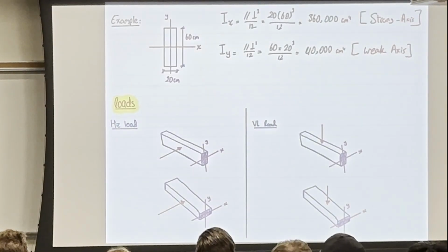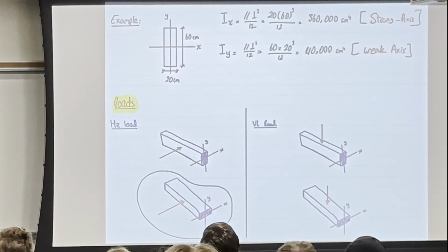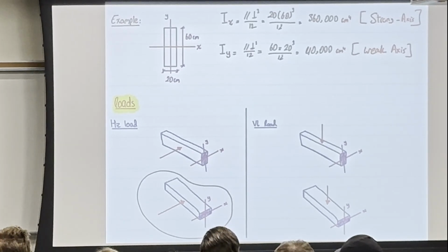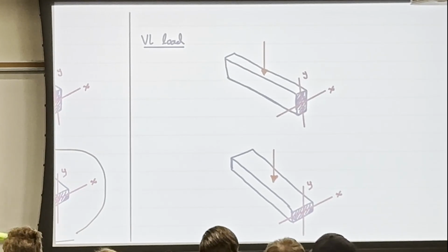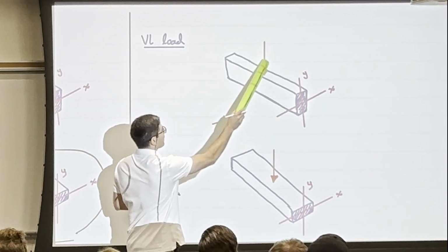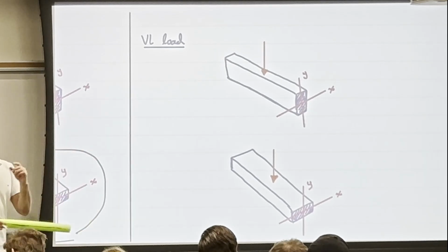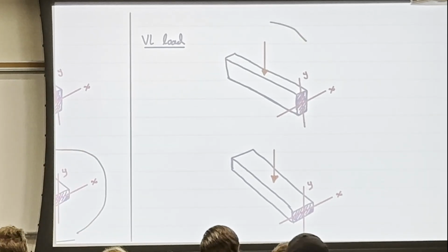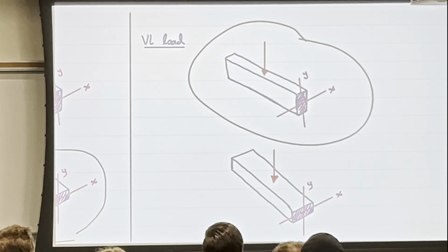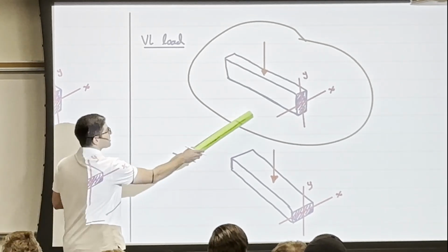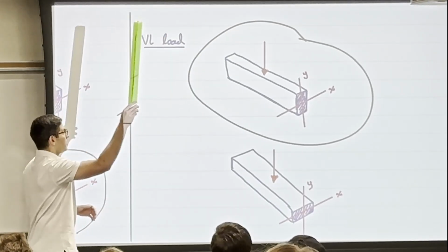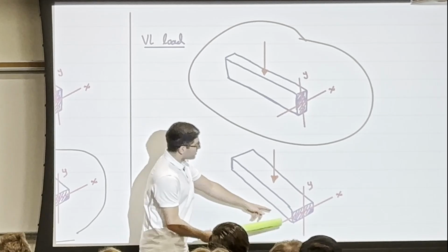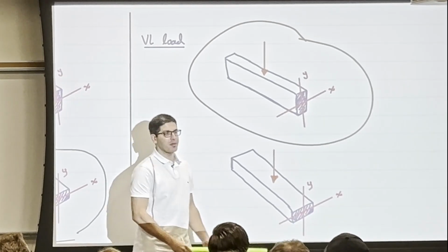This one we would choose most of the time. I don't want to say all the time, because we go down to this vertical load. What is the more effective way to align this beam to that load? The first one. The reason I say not all the time is that, like the beam above me, the engineer couldn't increase the height of that beam.